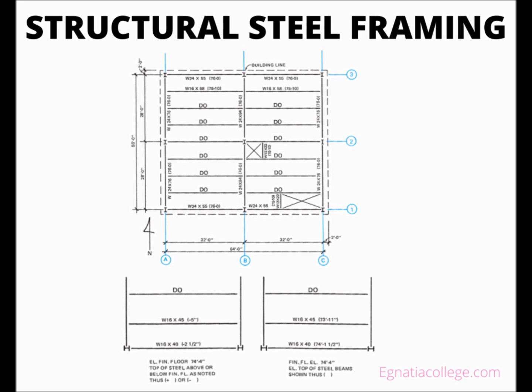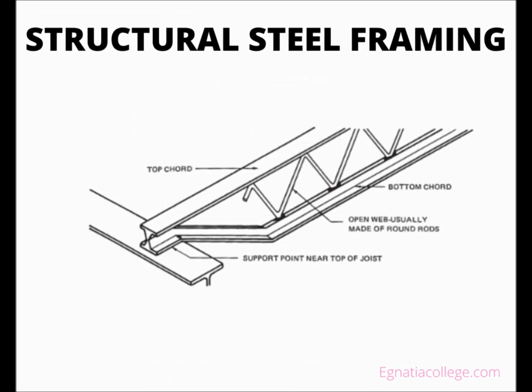Joists are frequently open web steel joists, sometimes called bar joists. Bar joists are manufactured in H, J, and K series, depending on the grade of steel used and their strength requirements. K series are stronger than H series, and H series are stronger than J series. A bar joist designation includes a number to indicate depth, a letter to indicate strength series, and a number to indicate chord size. For example, the designation 16H6 indicates a 16-inch deep H series joist with number 6 chords.